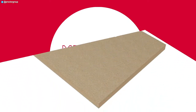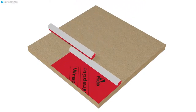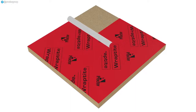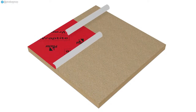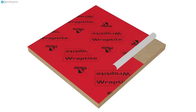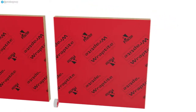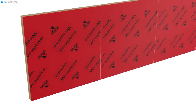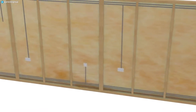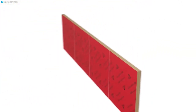fixed membranes. The membrane can be applied to the new panels in any orientation, and being self-adhered requires no mechanical fixings. This adhesion reduces the potential for membrane damage, both during the module assembly process and whilst in transit to site. The panels are then assembled and the joints taped using the same material in tape form, ensuring no adhesion issues or tape compatibility problems. Once the joints are taped, the panel assembly is resistant to air leakage, and any service installations such as wiring or pipework can be undertaken independently without risking damage to the airtight layer.